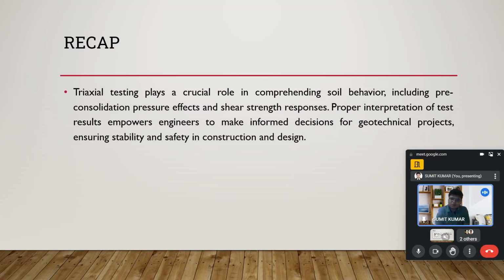So it becomes very important to understand the cases, specifically when we talk about loose and dense sand, or normally consolidated and over consolidated soils, which we discussed. There is a representation also shown of how the variations take place for the axial strain with the shear stress, sigma 1 minus sigma 3 by 2. So those considerations are taken into account during the discussion.